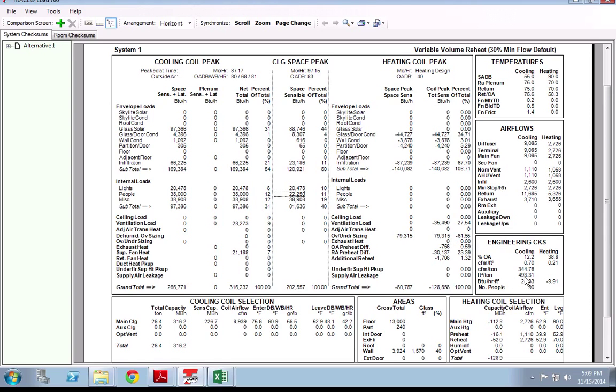Let's see, the square foot per ton, so we're at 500 square foot per ton, pretty average. I would say most generic buildings that have poor envelopes can be close to 300 square foot per ton. We really want to aim for 1,000 square foot per ton as our design goal for all our buildings. And it is climate dependent, so that may not be possible in the middle of India, but you never know.